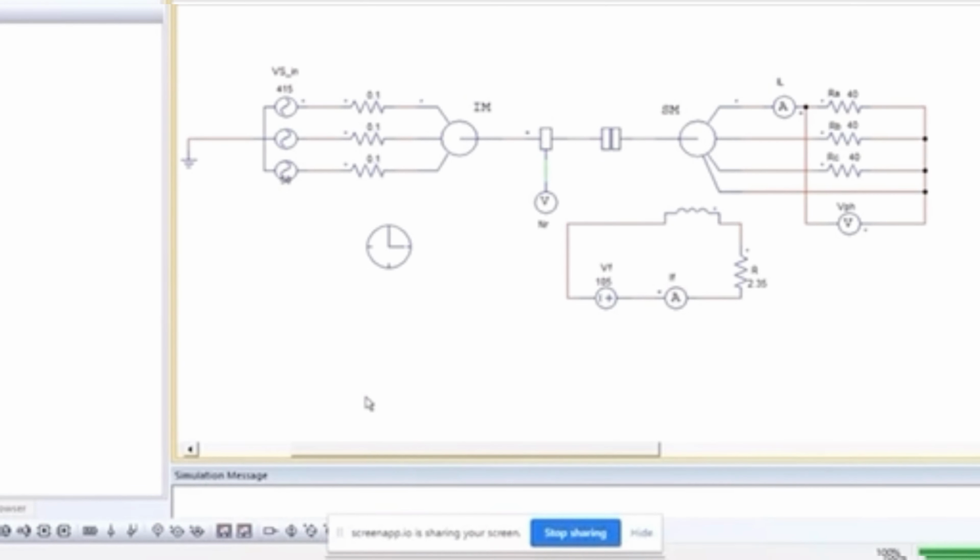Today I would like to present my part for the lab modified three-phase synchronous generator part 2. For part E, we need to find the rotor speed for the R load, RL load, RC load and RLC load. This is the example of the R load. We use the resistor 440 ohm and VF 105 volt.